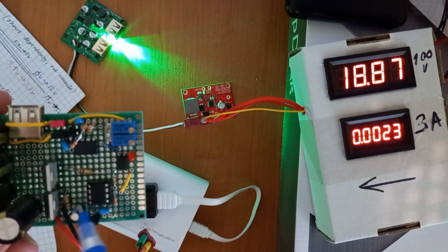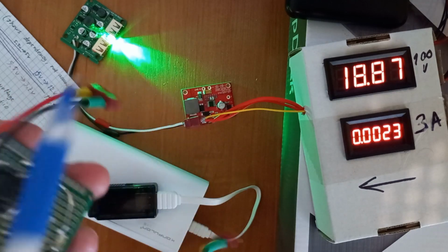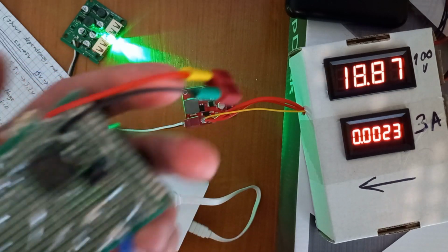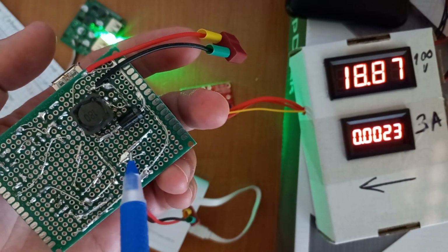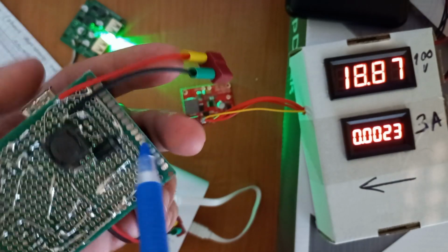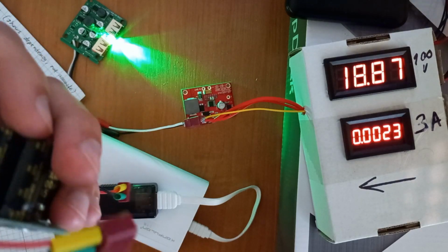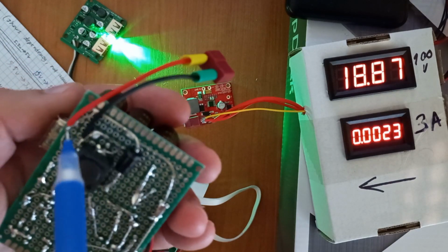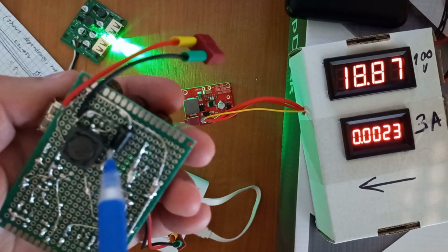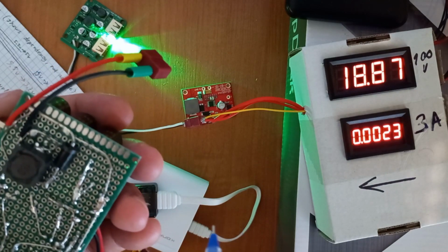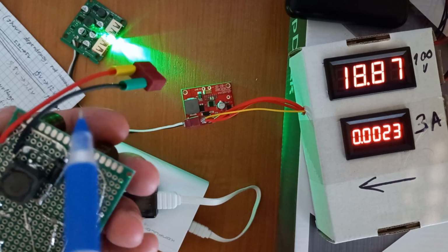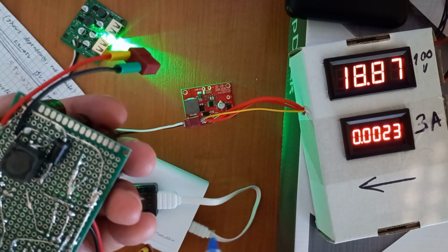Dense layout of the output buck converter circuits. Short power lines. There is a path for current to flow through the capacitors. These are the output capacitors, and current flows exactly through these. They are not somewhere aside. So for the capacitors, the in and out lines are separate.